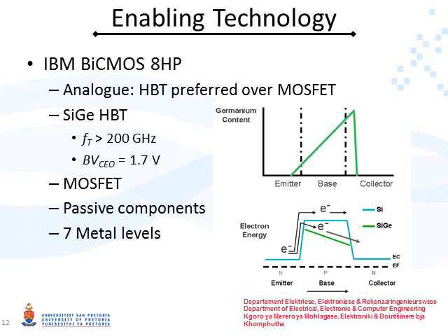Silicon germanium HBTs are formed with the grading of germanium across the silicon base, as shown in this figure. This reduces the band gap in the base region, resulting in the base transit time reducing. The net effect is that there is an increase in the transition frequency and current gain.